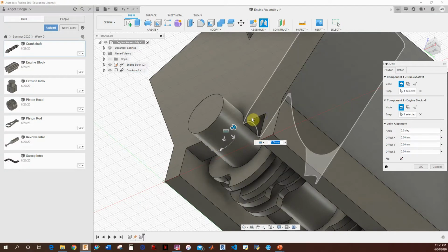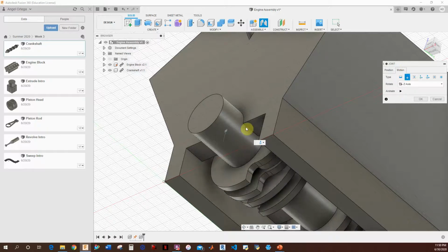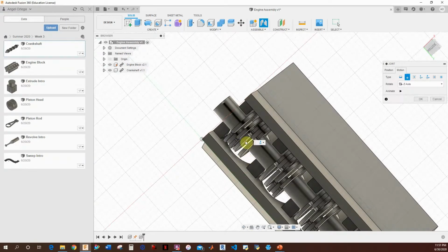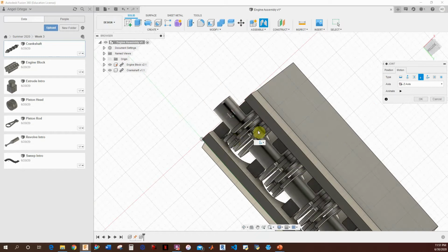As you can see, it sort of fits in, but in this case again, it defaults to rigid. Now I can try Revolute, and that seems to work. The only issue I have with Revolute though is that, as you can see, it's not perfect still, so it's not centered. So instead of doing a revolute, what I'll do is I'll allow this to be a cylindrical type of joint. So this will allow me that free rotation, which is what I want, but it's also going to allow me that free movement up and down that axis.